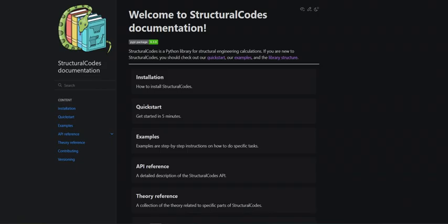So as I mentioned, we have the section. That's the ultimate level. Inside the section, you refer to a geometry, and the geometry refers to a material. And the material is a wrapper for basic ingredients from the design code. So a starting point for adapting this to any of your special needs would be to, for example, create a class. So my special concrete, for example.